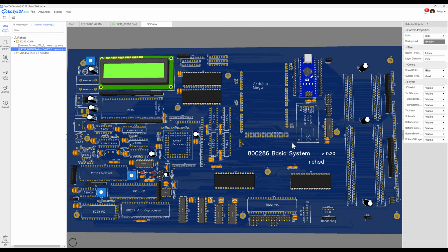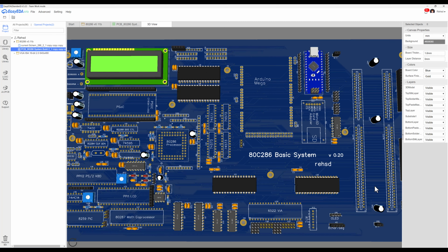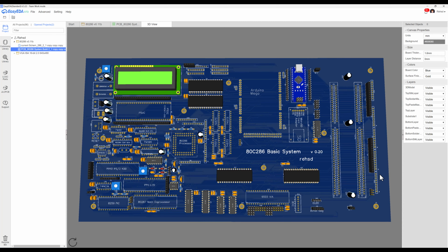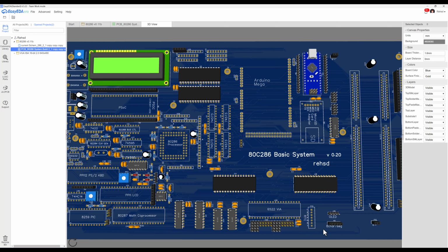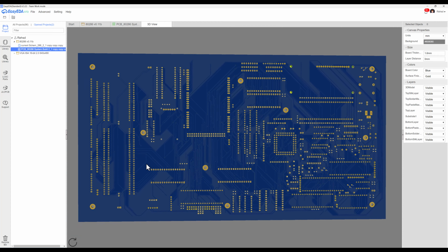But I figure at least this is probably helpful, that it can now get VCC through all of this, all around the board. So it's closer to getting into, for example, down here, I can now get into my ISA slots with a cleaner power. All these things down here now, hopefully, will have better power access to them, and when they aren't coming down to this, at least there's this 1 millimeter trace now. And then the same thing on the back, I could look for those 1 millimeter traces or see if things are getting a nice ground wherever they might be using them.